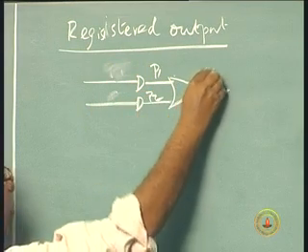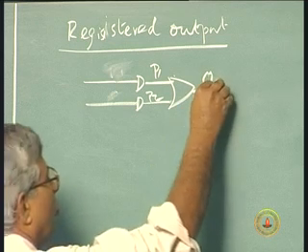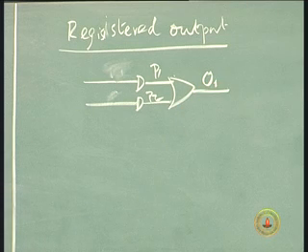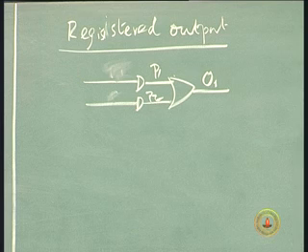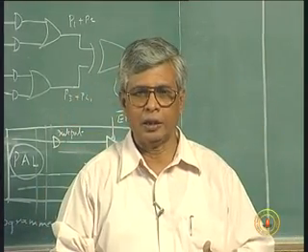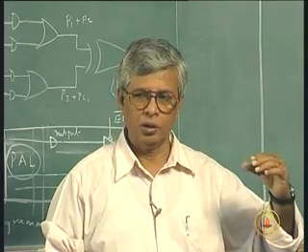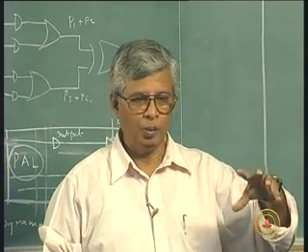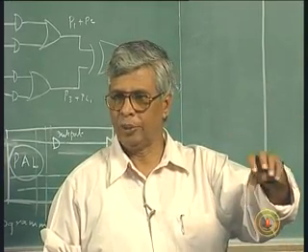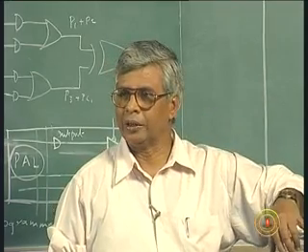This is my output 1, O1. I want this to be my input of the flip flop, and the flip flop will be the state variable which will be fed back. Is it not? You visualize that standard sequence circuit block diagram. We have the steering inputs, steering logic, output of the steering logic is the next state information which goes in the flip flops, which becomes a present state after one clock cycle.